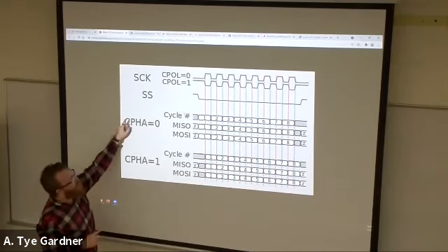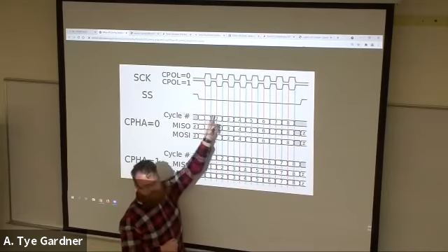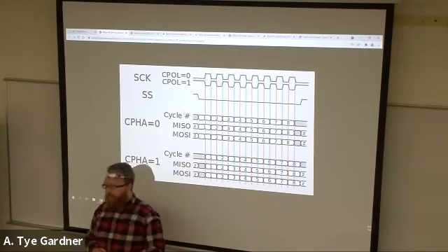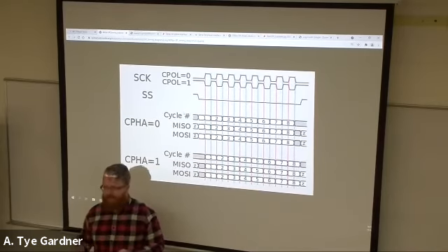So if you look here and you have a rising edge of this clock, because we're on 0, you will take data bit 1. You will read whatever's here. This bracket looking shape is a bit, part of the payload, that is either a 0 or a 1. Rather than writing 0, 1, 0, 1 arbitrarily, they use this kind of shape. So what it's showing is that on cycle number 1, if they have the rising edge, let's take this on the MISO, right? That's all it's saying. That's as far as you really need to care about.